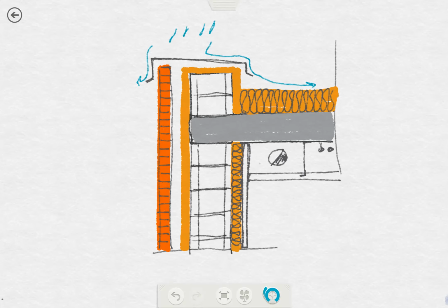So you know that we have the concrete masonry unit. If this is a bearing wall, if the concrete masonry unit is the structural element, we need to rest the slab on the concrete masonry unit here. Why? We need this on the concrete masonry unit, and then we need the parapet. So we have to continue the concrete masonry unit here.